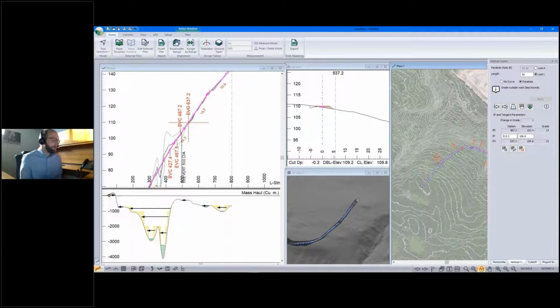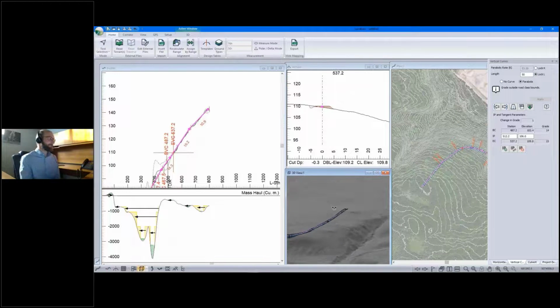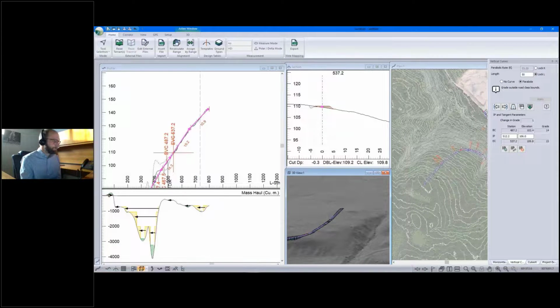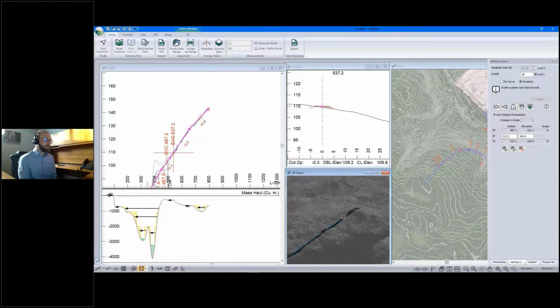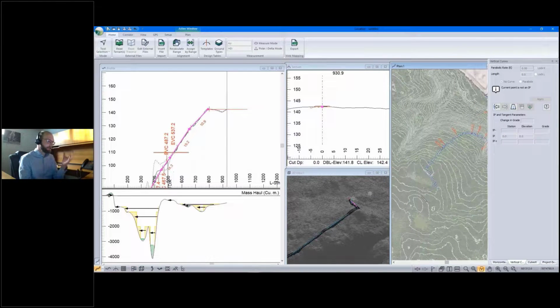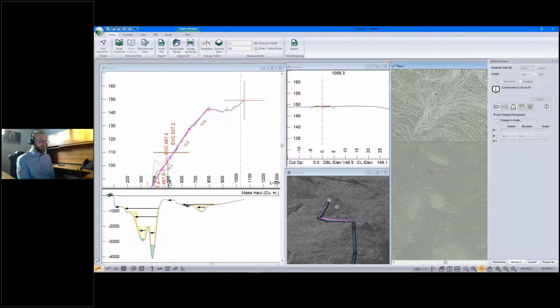So in this example, I've got the gnarly stuff done. Please don't think that just because we're done the steep stuff, you can put a straight line to the polygon that we brought in and bingo bango. Flat terrain has its own set of challenges. Usually the biggest challenge is going to be managing drainage. So usually my go-to strategy for that is, well, let's ride the ridges as best we can.